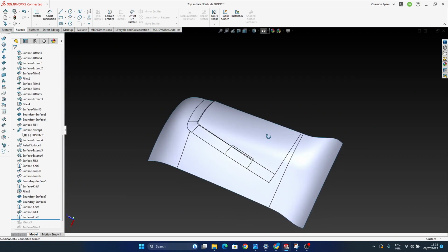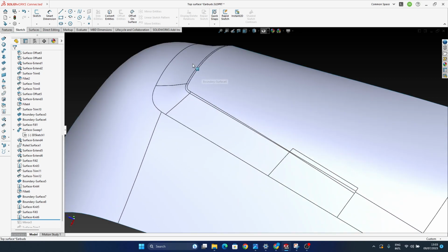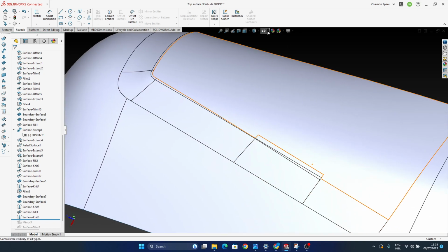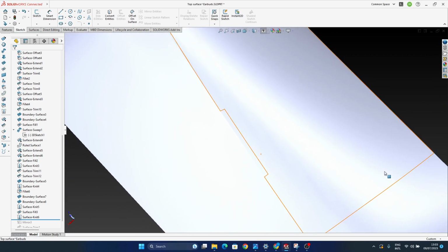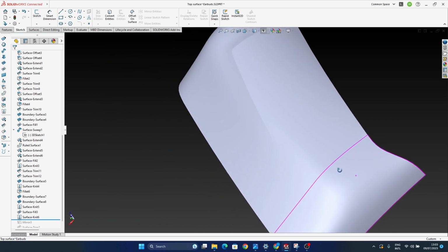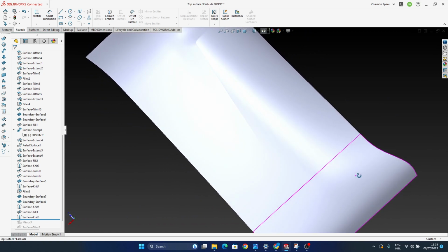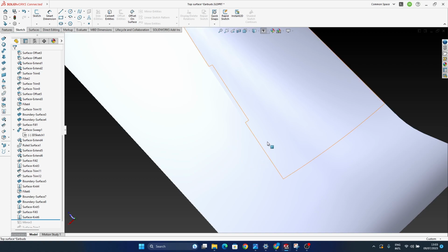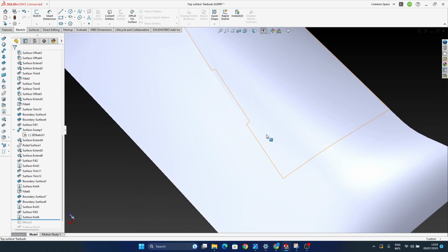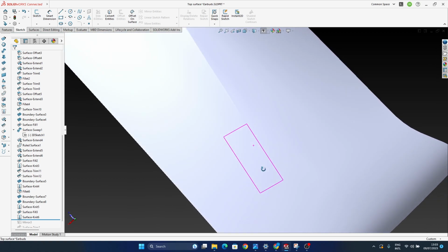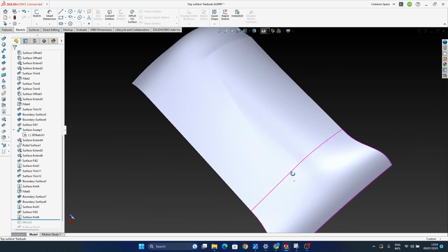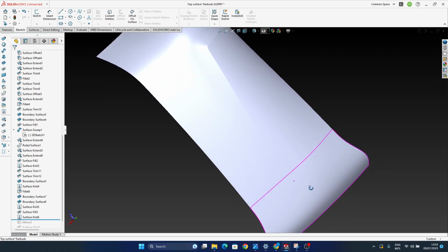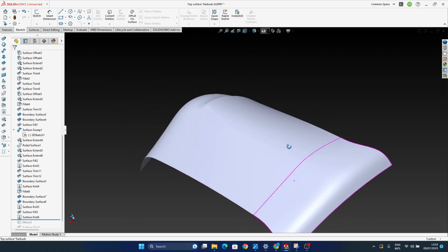I should be able to see this fillet done nicely, fading away towards the middle, or fading away towards wherever I said I want to fade away. But here towards the end, where I'm having these surfaces joined like that, I should be able to see no edge anymore in the reflections, and that's all right.